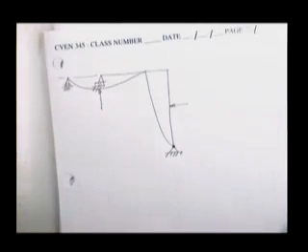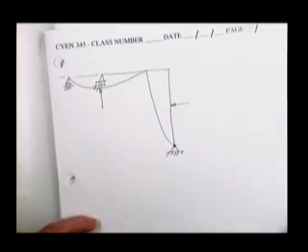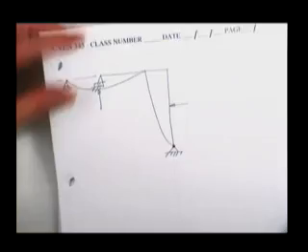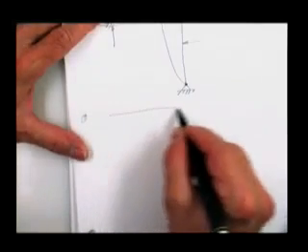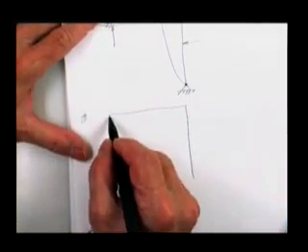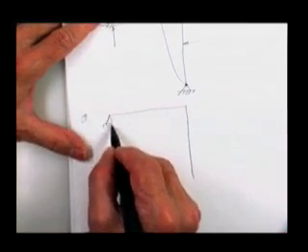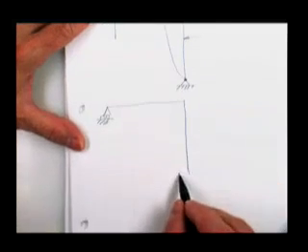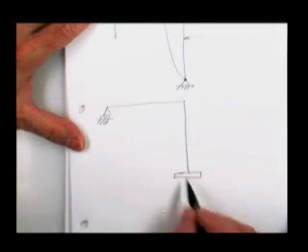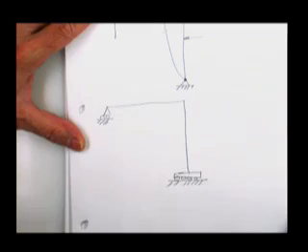Now, I don't suggest you go off and get a weird primary structure just to make your life more difficult, but they are all good primary structures. Any one of them that you can, as long as it's stable. Now this one's not good. Remove one reaction, so I'm going to leave this. I'm going to put a thing here which will take axial force and will take bending, but the thing I removed is the horizontal force at that point.